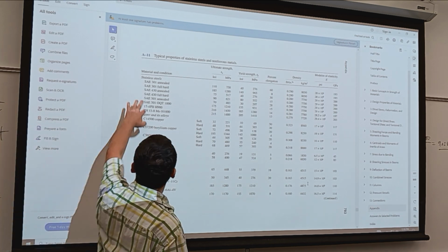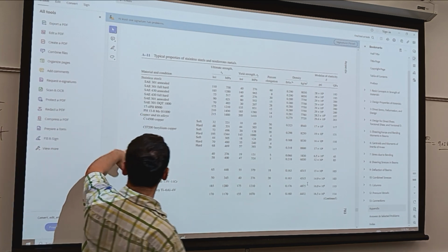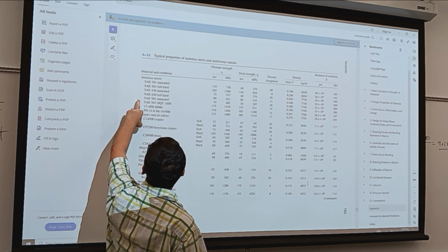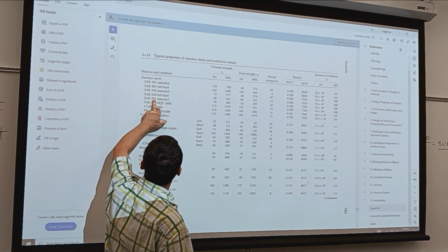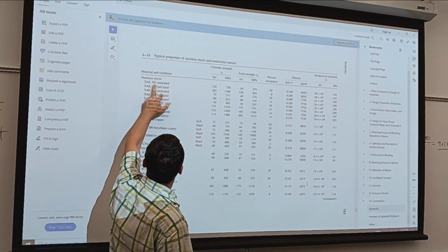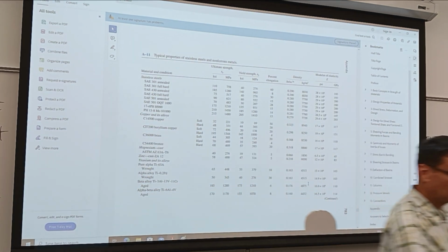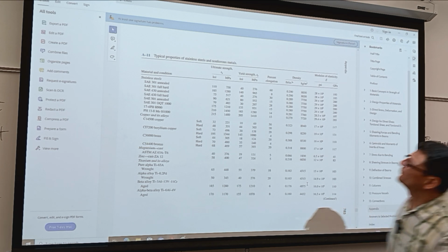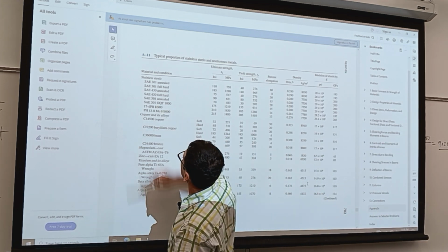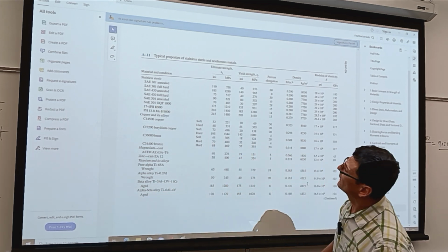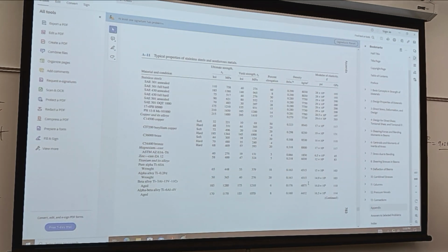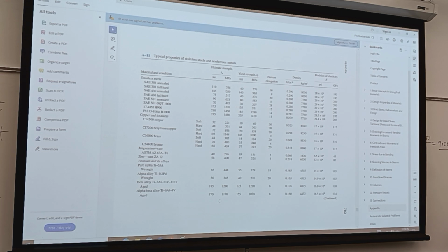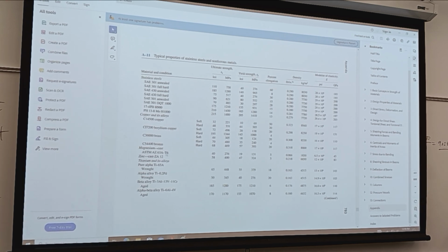Okay, so we have the stainless, and some of them are called austenitic, and the magnet doesn't stick to them. Cutlery is a different type of stainless, and it's magnetic, but the austenitic is non-magnetic. And then we have copper and bronzes. Bronzes are alloys of copper and tin, and brasses are copper and zinc.